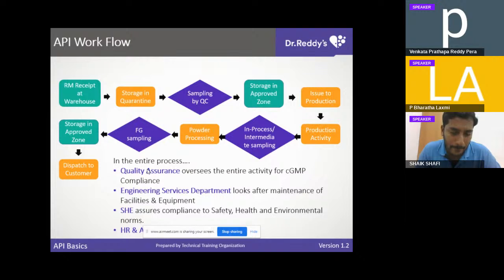Next question, Shafi: what is the difference between a pilot trial and a plant trial? It's the same question which was asked last time. In the pilot plant, we did lab trials in glassware. Coming to the pilot study, the small equipment used in the process is taken into the pilot plant, then we start increasing our batch size and throughput and cutting down cost.